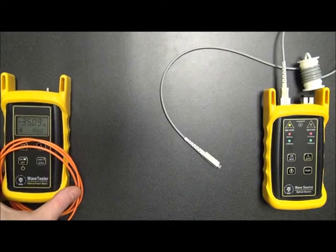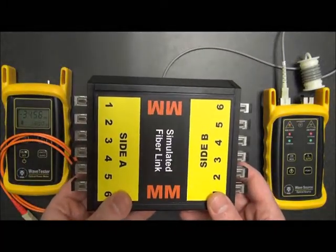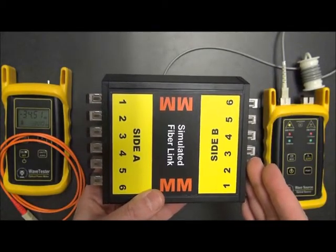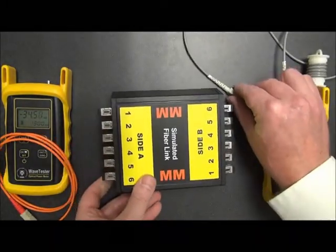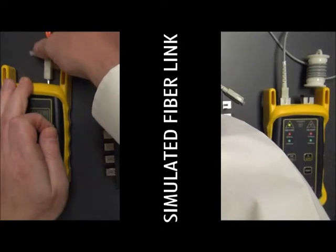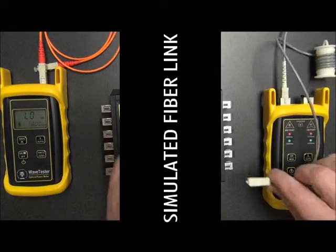So now that we've taken our testers to opposite ends of the link, it's time to connect these testers into the link. Now what I've done here is I have a box here that simulates a fiber link. So let's say side B is a six-port patch panel in one closet, and side A has a 6-port patch panel in another closet. So what we need to do first is connect our patch cables into port number 1. That's usually where we start. So we just take the dust caps off of port number 1, and we plug in our testers to port number 1.